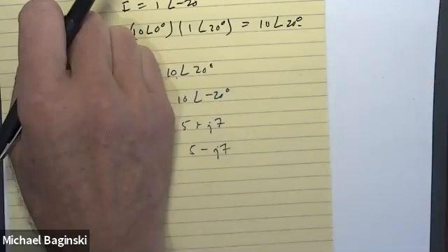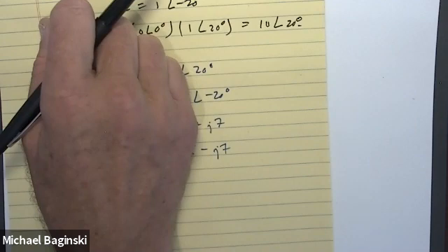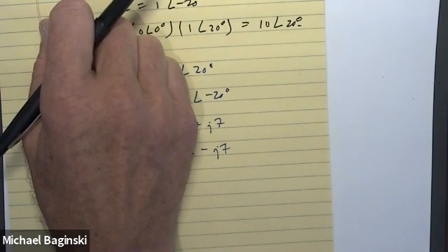You all realize that you would like the power factor to be 1. In other words, the difference in phase angles to be 0, if you were running some sort of a power plant, because the further off your plant is from having a cosine of 1 for the power factor, the more money you're going to pay. That's what it comes down to. It's always a cash game.